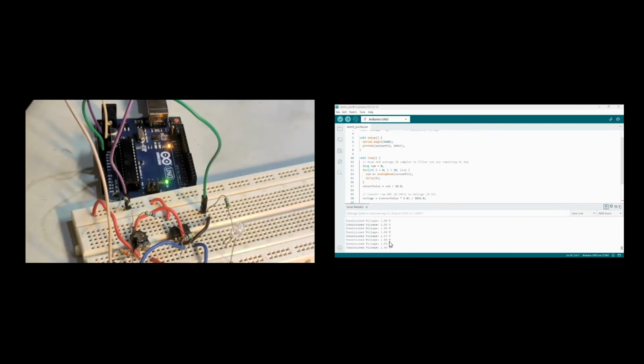As we have kept it here, only then are we getting this voltage. And on the serial pin, the voltage is displayed, and we are converting temperature to voltage gradually with the help of a Wheatstone bridge. That is called active signal conditioning. So this is a new topic which is important, and that's why I thought I would make a small video on this and try to teach you.